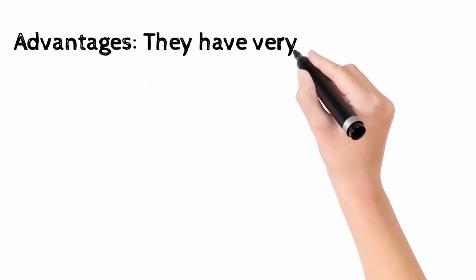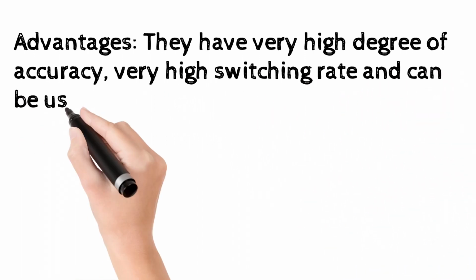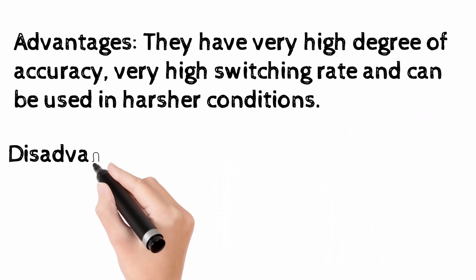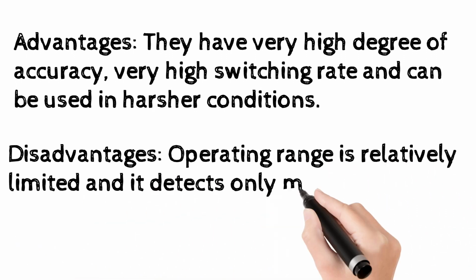Advantages. They have a very high degree of accuracy, a very high switching rate, and can be used in harsher conditions. Disadvantages. Operating range is relatively limited and it detects only metallic objects.